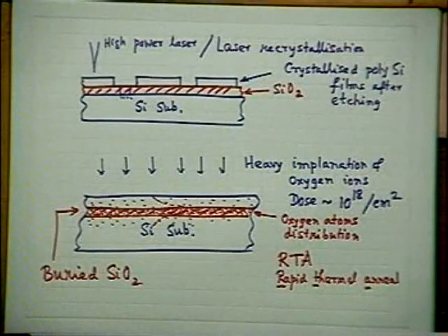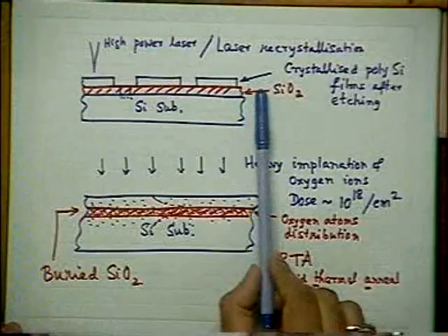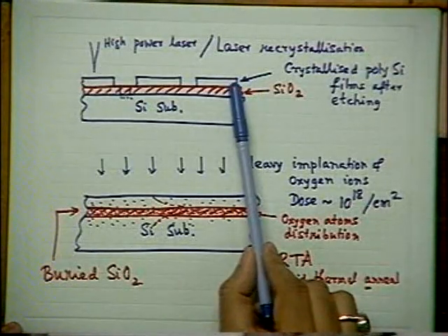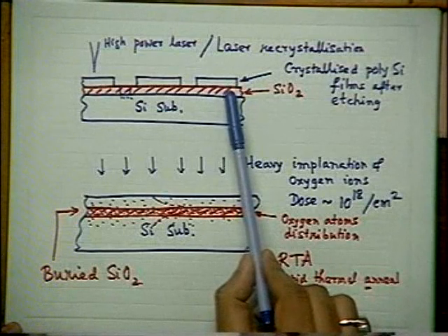And that's why layer by layer you deposit a good quality film for epitaxial growth. But if it is an amorphous material, say an oxide layer, an amorphous oxide, not silicon, then it is not getting regular nucleation sites. Therefore, the growth will be random, and we get polycrystals. And if you do the same deposition at a very low temperature, around 500 degrees centigrade, the film is amorphous in nature. There is practically no order.